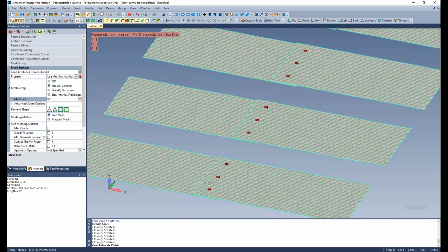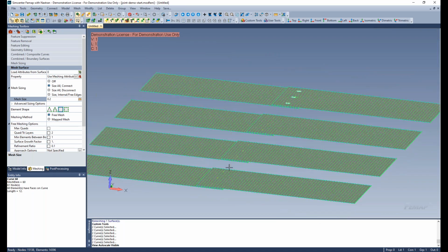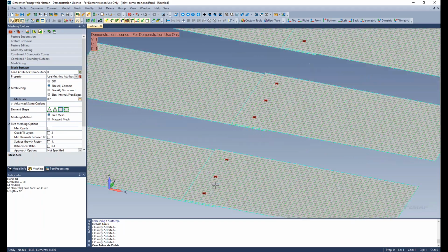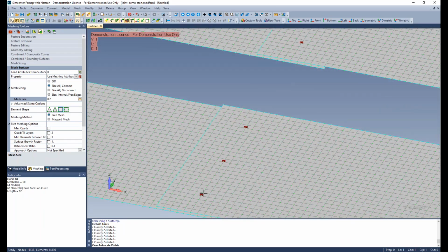I have an API that I was sent that does that, but it's an API, so there is no built-in way in FEMAP. Recognizing that that would be helpful, they said they'll try to add that to FEMAP. So that's why I said earlier, you probably want to keep track of things with groups if you can, so that you don't have to figure out which nodes are which.